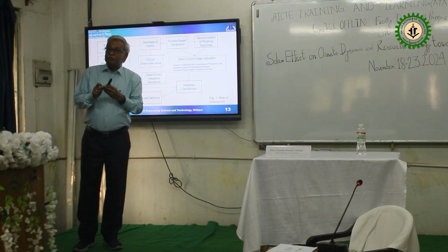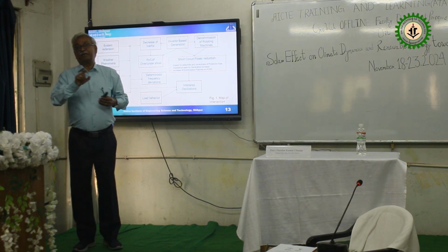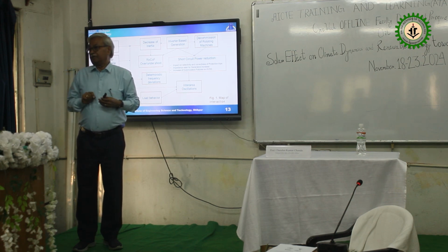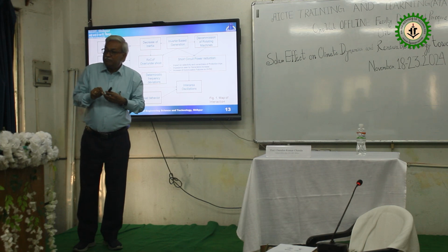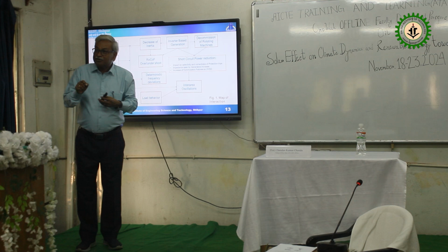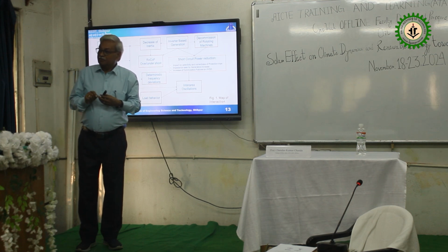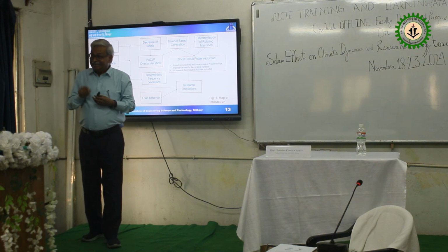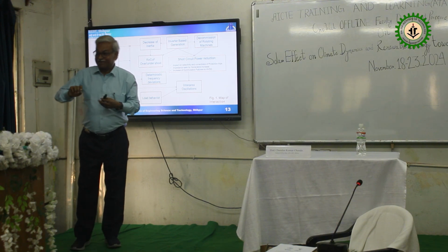If you studied that chapter in the 5th or 6th semester, we talk about the frequency deviation, delta f: how much frequency is deviating from the standard value. But nowadays, we do not talk only about the change of frequency, rather we talk about the change of frequency and its rate, d(delta f)/dt. That's the important criterion of penetration.